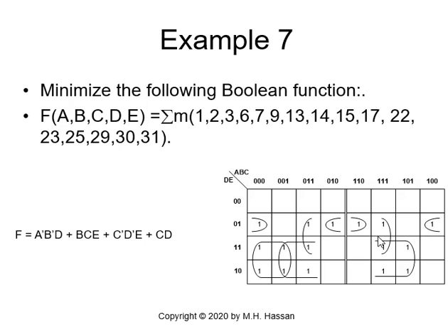And the same thing with this one, the set of 8 will give me CD, because vertically the E will cancel out, so I will have D. And we get C because again A and B will be cancelled out, so the only thing left, C is 1 here, C is 1 here, C is 1 here, and C is 1 here. So yeah, I have to be very careful. So I will generate CD for the set of 8.